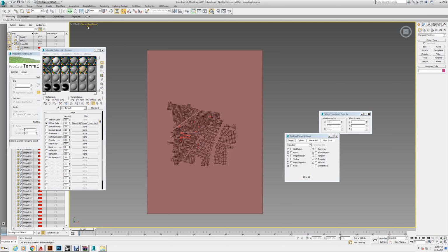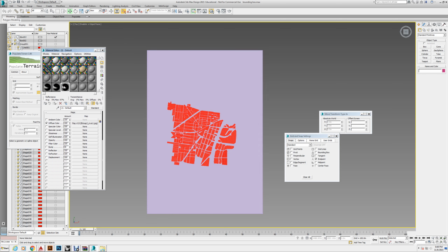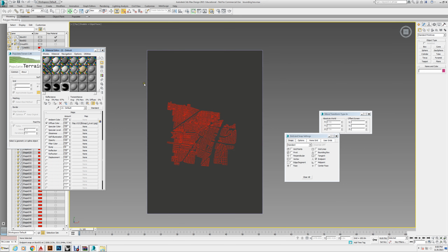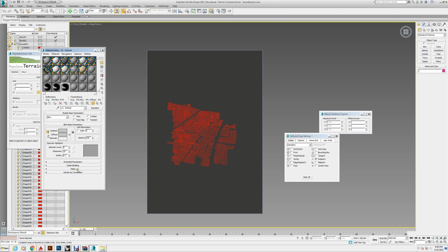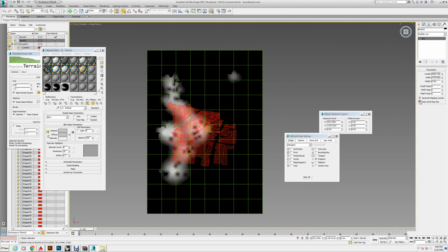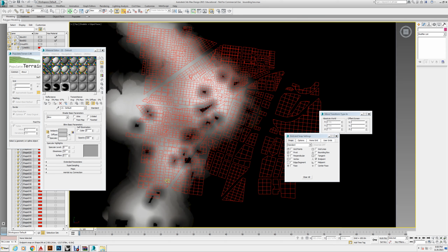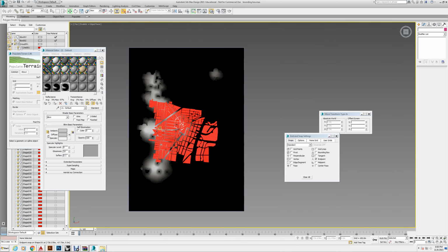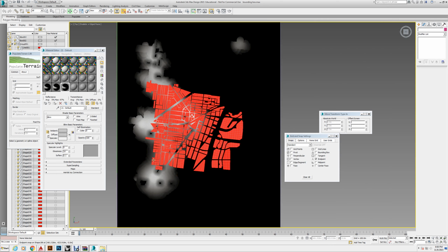let's get this happening. Okay, so I have already created a new material, and I've put our walkability visual into the diffuse. So we want to bring that here. Let's just close that. We don't want to use real world mapping. There we go. So we can see our site on top of the walkability intensities.